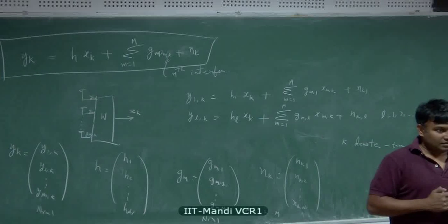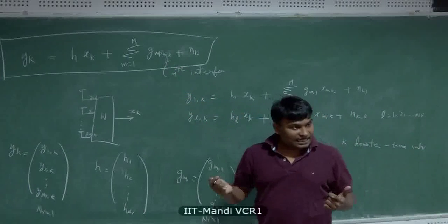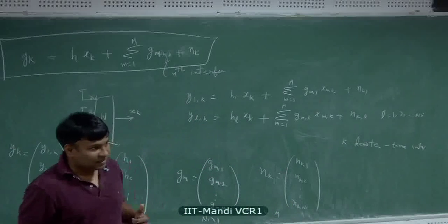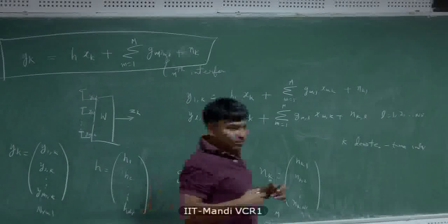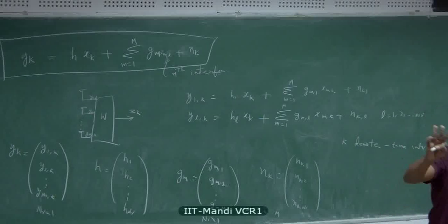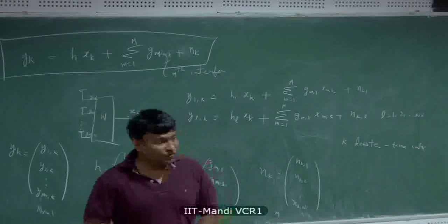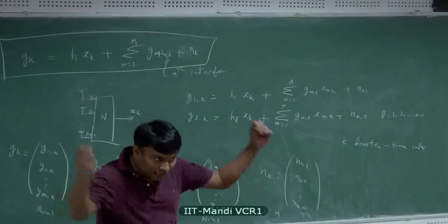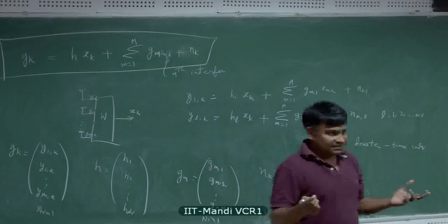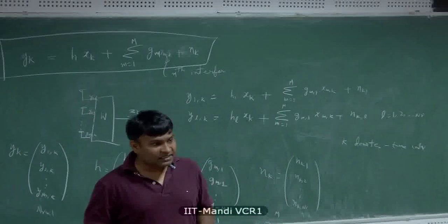But aren't those sources coherent? Isn't the same symbol being sent by all of them? No. If the same symbol is sent, then there is no advantage, right? You have to then capture that and combine it with the symbol. The point here is each transmitter sends different data. Then you can increase the data rate. If you send the same symbol from transmitters that are located far apart, then you can combine those paths and get some benefit. But we are not interested in that sort of benefit. That's very limited in nature. We are trying to increase the data rate of the system.